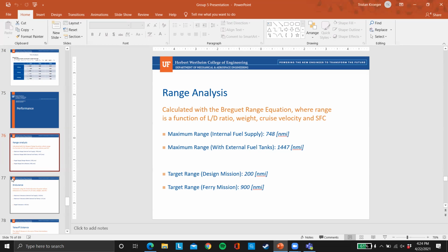Yeah, so make sure that if you really have the external fuel tank, it should be a different connecting point from the weapons. Weapons have their own connecting mechanism, how to eject your weapons and everything. And the fuel tank should have its own mechanism, how the fuel feed system actually pours the fuel into the engine, right? So they're not the same point. They're not interchangeable.